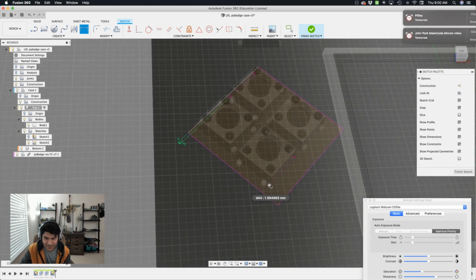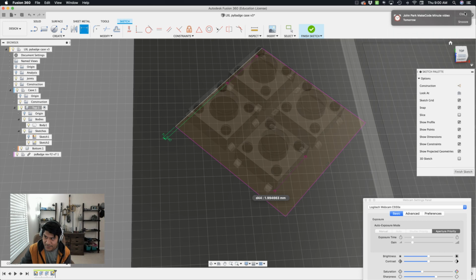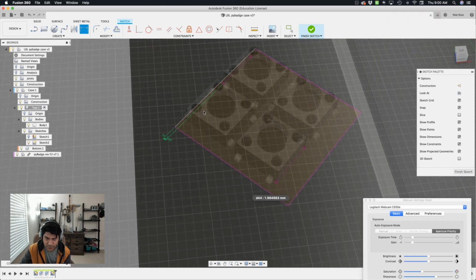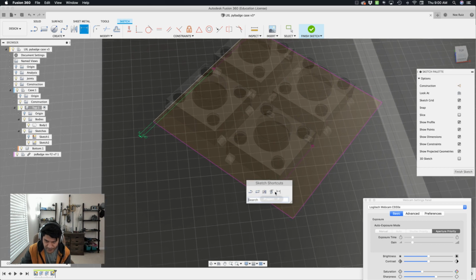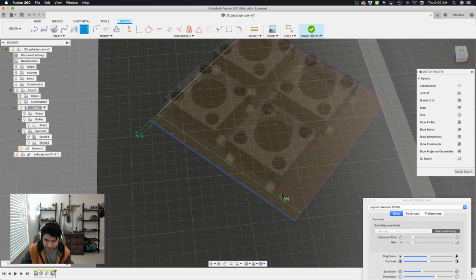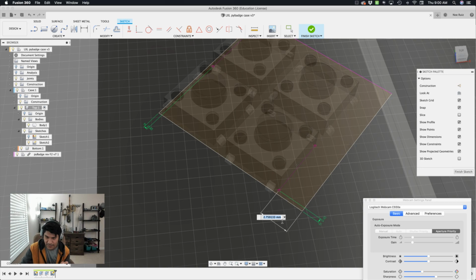All right, so then looking at this one here, we can see there's no line here, right? Well, we don't need one. We can just say, I want to dimension this line away from this point, and that way I can just leverage that one line that has those two points as opposed to having to create a whole new one. Again, I'm using that little trick here where I hit the drop down and just select gap, and then I hit enter. And then this one over here, we can use the line. Same thing, click on the arrow, gap, enter.